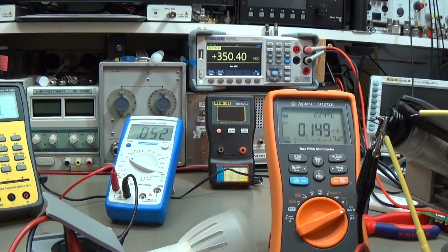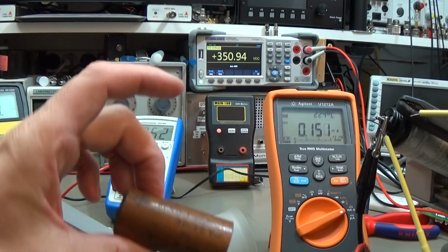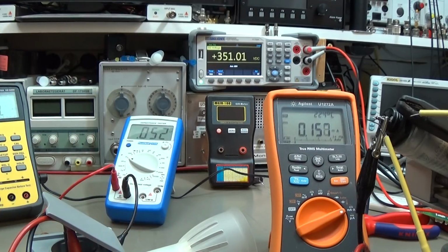And we have seen that we can use, of course, our ESR to get an idea of the condition of a capacitor. So we see when the capacitor starts aging, and we know when the ESR is really rising to a high value, then our capacitance will drop down, as we have seen it here with our old types, right?